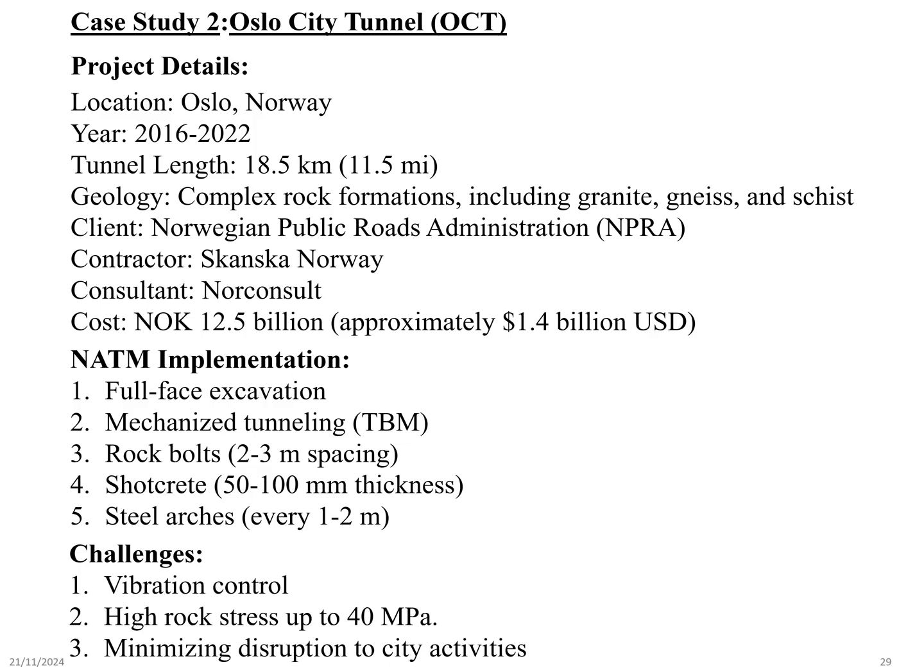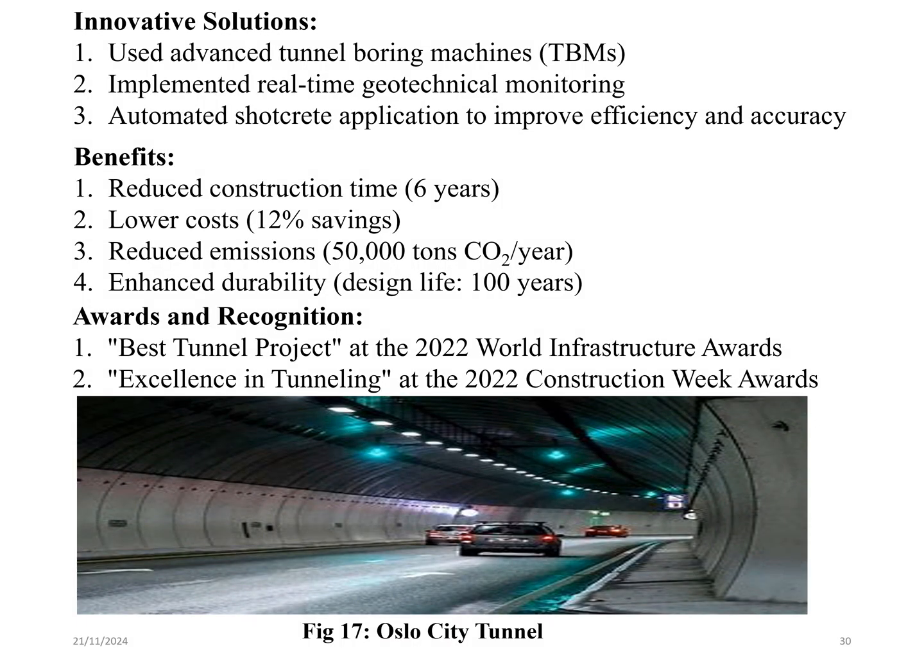Challenges faced: vibration control was essential to minimize the impact on the surrounding structures. Managed rock stress up to 40 megapascals. Ensured minimal disruptions to the city activities. The innovative solutions: advanced tunnel boring machines were used to enhance tunnel efficiency, real-time geotechnical monitoring improved safety and decision-making, automated shotcrete applications increased efficiency.